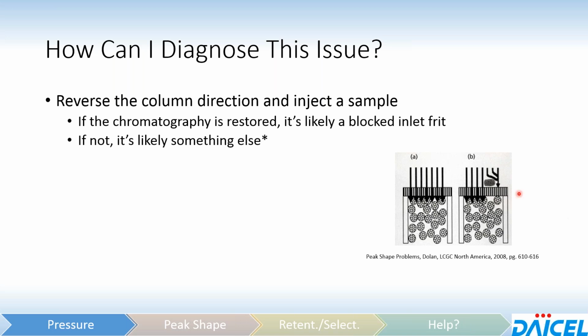But again, I have the caveat here that if it is not restored, it could still be a blocked inlet frit. However, the inlet frit might just be so blocked that even at the outlet, the change, the slowdown is dramatic enough to continue to show the split peaks.